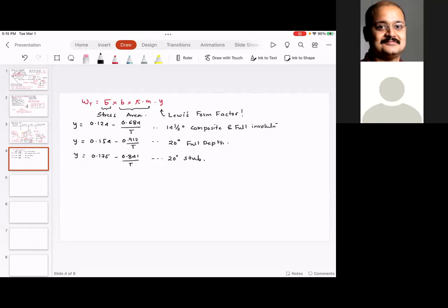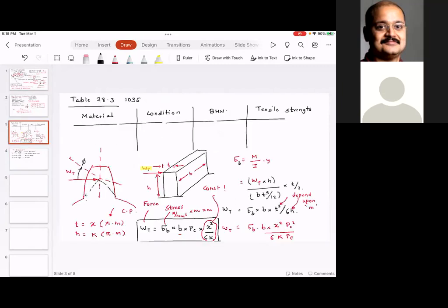So let me repeat this once again. Look at the beam equation that we derived. Here, we did not assume the load to be changing, or moving, or varying either in magnitude or in location. But when you are looking at the actual gear meshing, you have some dynamic effects.